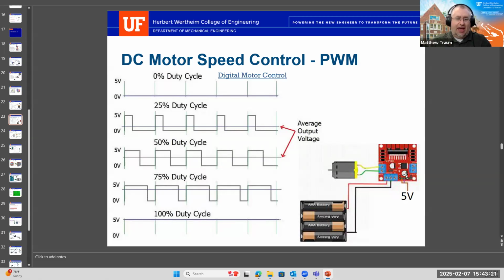That pulse width modulation is controlled by something called a motor driver. You feed power to run the motor into the motor driver. You run the logic of the motor driver off of a 5 volt signal, and the motor driver will do all of the pulse width modulation calculations and signal sending for you. You just need to find an appropriate library, drop that into your code, and say, "Hey, motor driver library, run my motor at this speed and this direction."